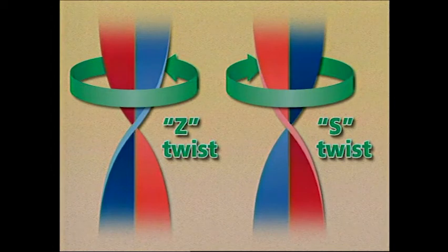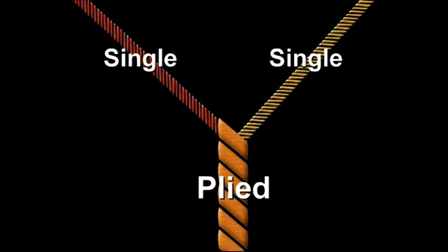Cotton singles yarns of high twist will yield greater skewing or torquing of a single knit fabric. Twist multiple refers to the level or intensity of twist and has an impact on skew and fabric softness. Twist has a marginal impact on shrinkage. Yarn configuration relates to whether there's a single strand of yarn, two yarns plied together, or two single yarns knitting together. These relate to skew, costs, appearance, strength, and hand.